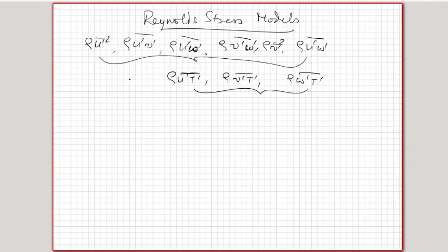So these are again called Reynolds stress terms, but they are the Reynolds flux terms actually, and these are the Reynolds stress terms in the momentum equations. So now if I have to solve for a 3-dimensional flow in which I don't want to assume isotropic conditions, then I'll need to solve for these 6 plus these 3, a total of 9 extra unknowns.